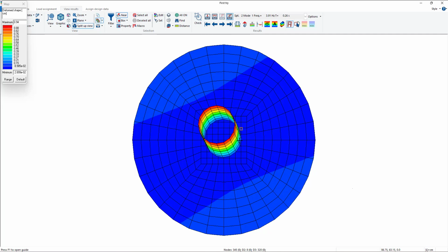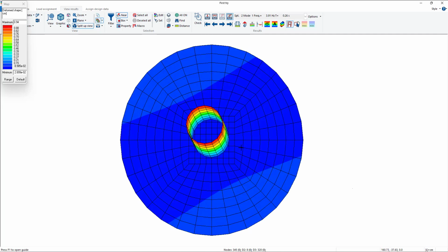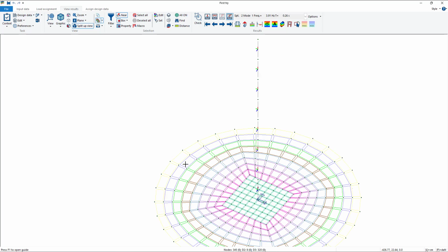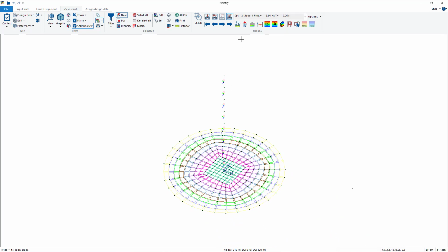It's always true that you should try it, you should model something and go check it by yourself, basically. Other kinds of results that you can check are nodal forces, nodal translation or rotation, sorry. So the degrees of freedom of the single nodes. Here we have the result sections for those nodes. In this case, they are not available because we don't have any external boundary. We have no nodes fixed on the ground, so we cannot have results of this kind.